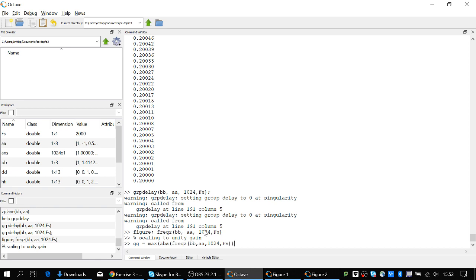It is exactly the same frequency response function you used to calculate the frequency response. If you use that one as an input argument, it actually returns the value. Then you can take the absolute value, which is the amplitude response part. The same way, if you call angle of the frequency response, that is the phase response part.